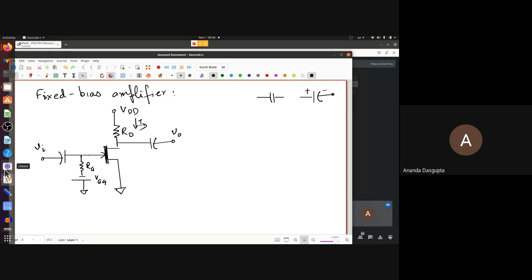No current flows, that's it. And if it is a non-ideal current source, it has to be replaced by its internal admittance, which is usually a very tiny admittance or a huge resistance. So that's how it goes.